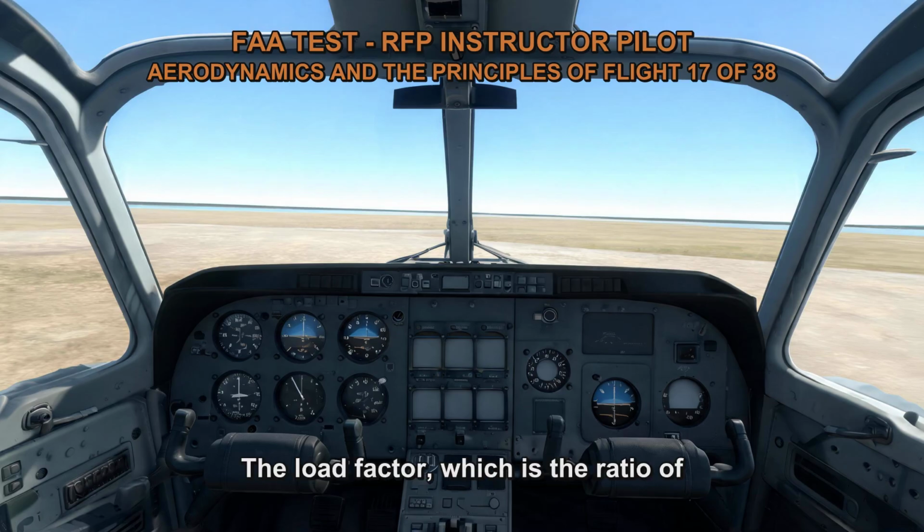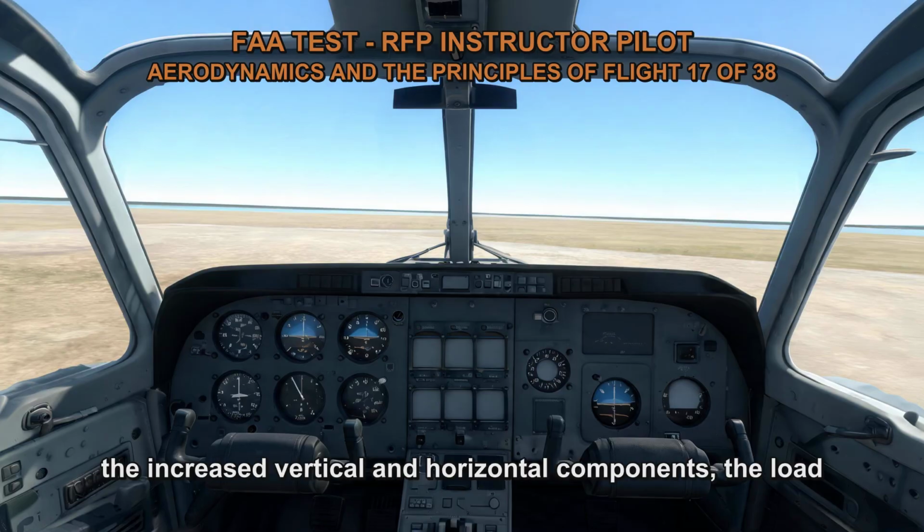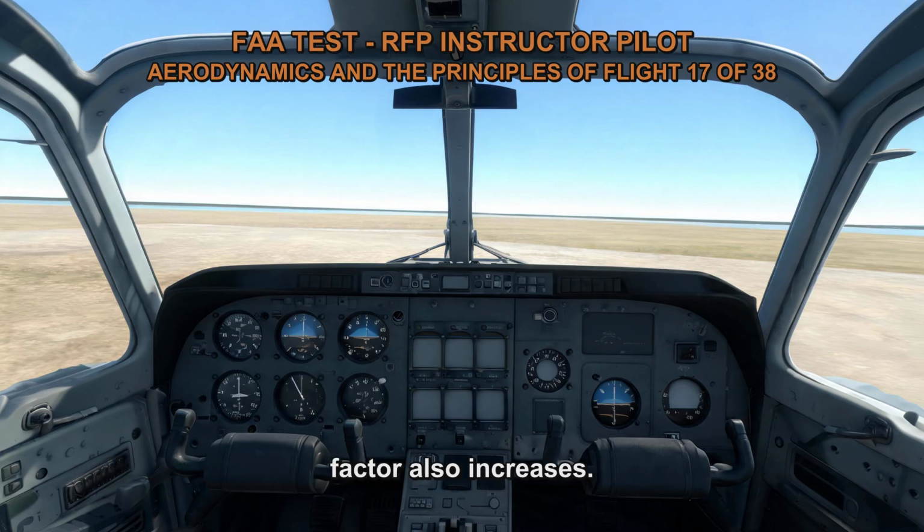The load factor, which is the ratio of the total lift force to the weight of the aircraft, will also increase in a bank turn. The load factor is directly related to the total lift force. As the total lift force increases to support the increased vertical and horizontal components, the load factor also increases. Therefore, the correct answer is the total lift force must increase, and the load factor will increase.